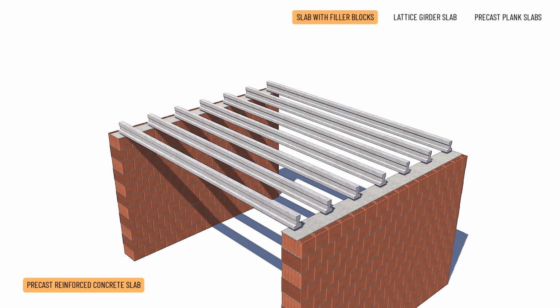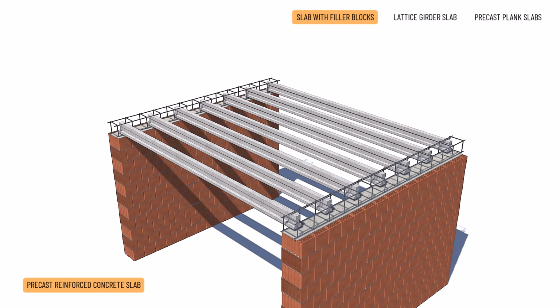The minimum bearing length of the elements on the wall is 10 to 15 centimeters, depending on the type and span. The ring beam must have unique reinforcement, and shuttering realized in a way to raise the beams 5 centimeters above the wall surface. This way, the lower longitudinal bars of the ring beam can then be placed under the beams, allowing them to be fully embedded.